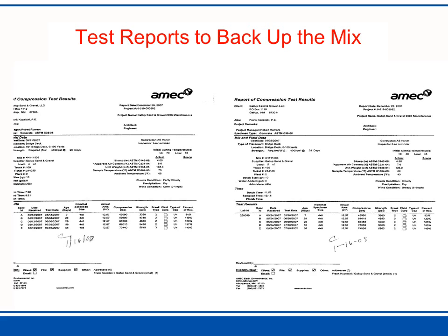I would get these from the testing lab that was on the jobs doing the testing, and I made sure that the testing labs had their people certified, and also that the cylinders were being properly cured the first 24 hours and taken back to the lab, and that they were cured, and that all the technicians who made the cylinders were ACI certified.